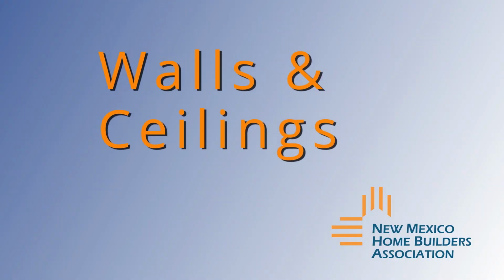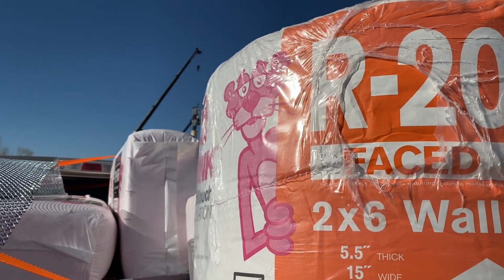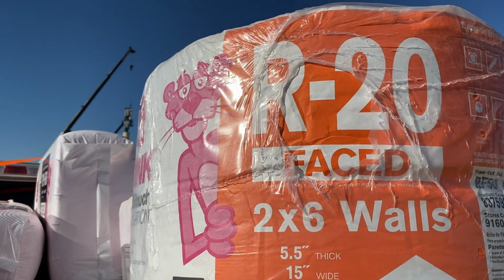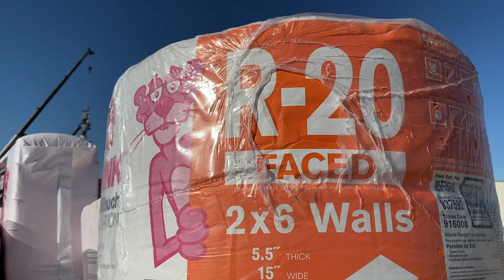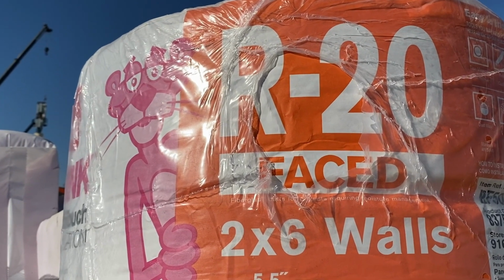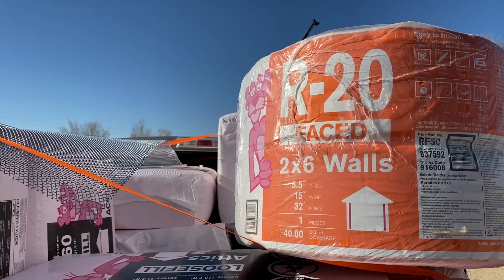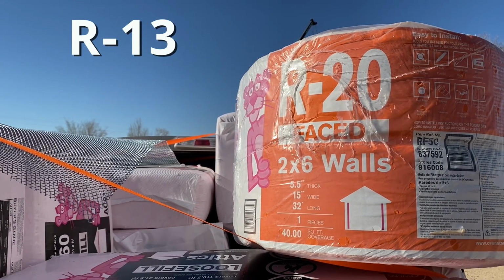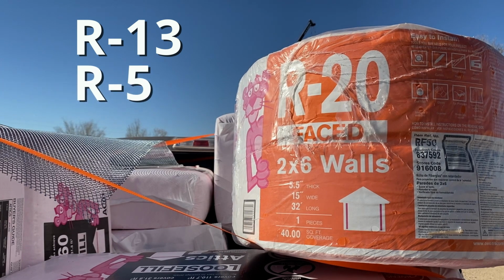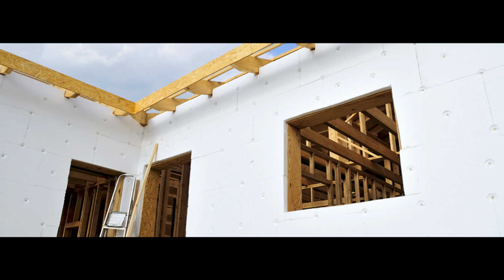The R19 in walls has been bumped up to R20. Be aware that if you are using 2x4 framing, you will have to change your building technique. R20 bats or blown-in insulation will not fit into 2x4 framing. You will have to either switch to 2x6 framing or use R13 in the walls with another R5 in rigid foam on the outside. Rigid foam on the outside requires other changes due to moisture management issues.